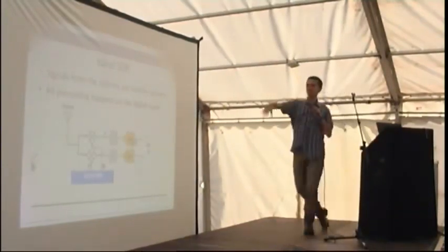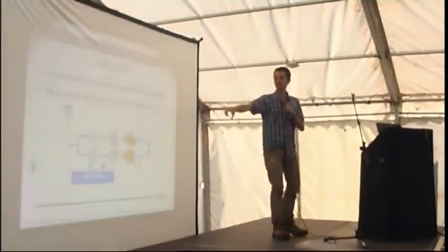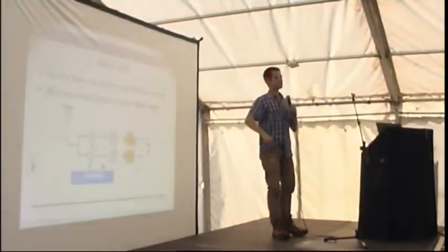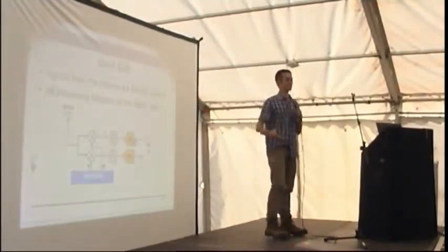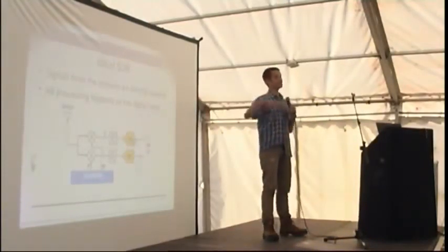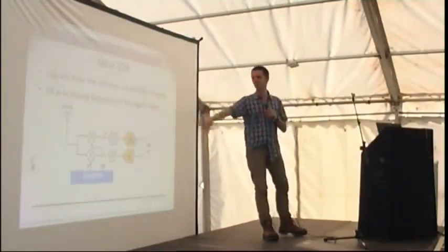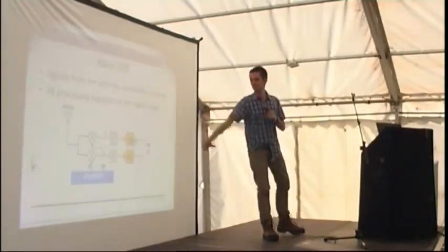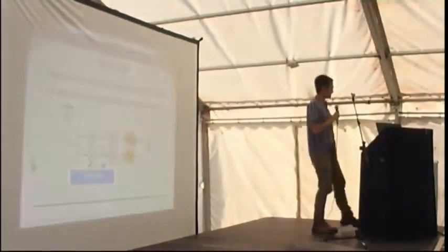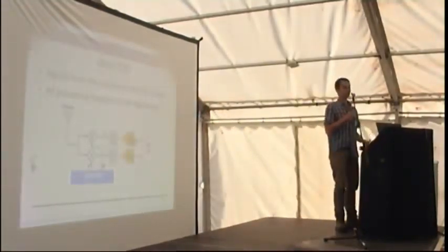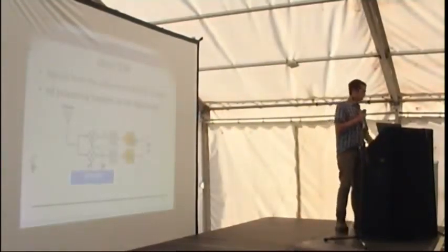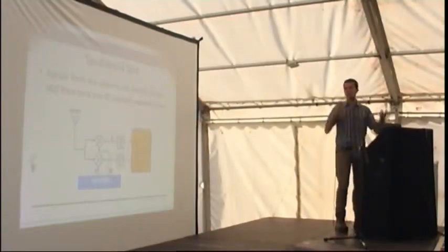So this is what an SDR looks like. It's basically an antenna, and then there's some mixing so that you can extract lots of information about the signal and accurately get the representation back, getting the amplitude and the phase and the frequency all in one go. And you filter, and then you convert analog to digital. But some of these SDRs you end up plugging in via an audio cable, and so we call this a sound card SDR.